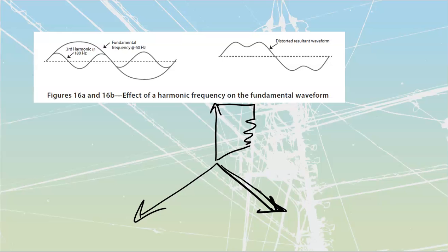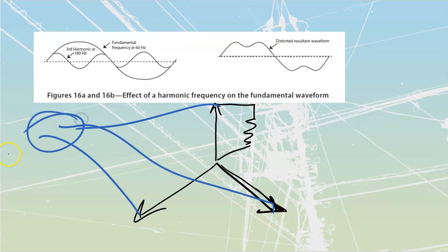If I get voltage imbalances, this is going to be from single-phase loads, but the problem is that if I've got a three-phase motor coming off of this same system, that three-phase motor is going to see these imbalanced voltages. As it sees those imbalanced voltages, it is going to get a big push, and then a little push. They're magnetic pushes, but they're still little pushes that we're getting all the way around the stator. And we're going to get weird operation. The motor is going to have a bit of a lurchy operation. It's sometimes going to have a different whine that you're going to hear.